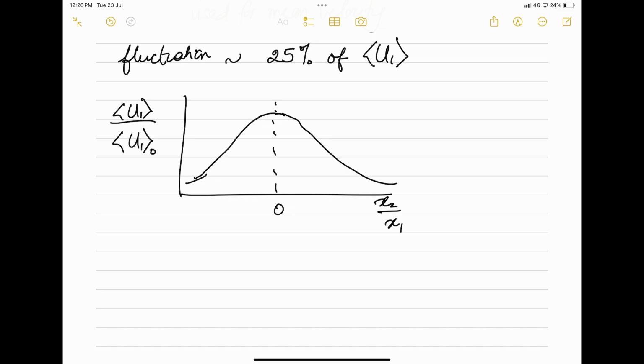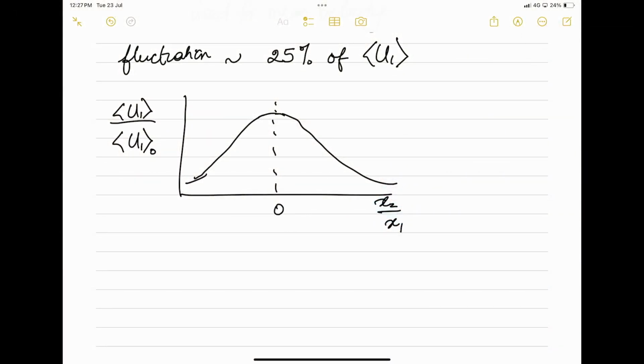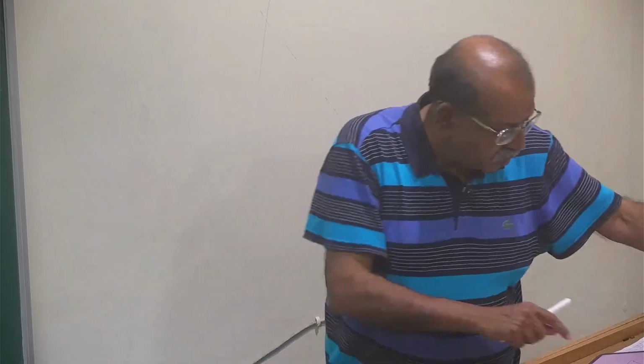And in this shape, what we realize is, in this average velocity, we do not find any jaggedness. The average velocity as a function of x2 is a very smooth curve, and it changes in a smooth pattern. It does not change the way the turbulent velocity changed or the fluctuations changed. So that is what we will try to figure out by the end of this course: in the turbulent flow, what are the features which go like this. Now, one more thing,